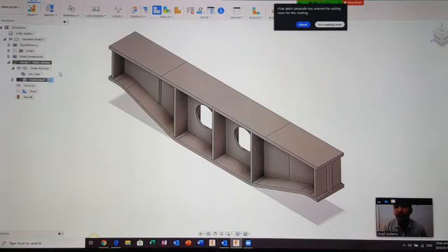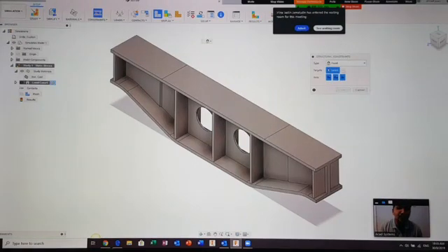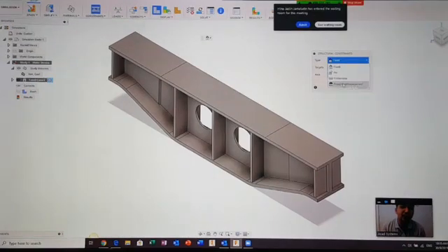Alright. So inside the cast iron material, it's already included with the properties needed inside the simulation environment. Okay, next, after putting the material, I will make the constraint. Constraint is where you want your part to stop, or maybe you want to fix the location of your part. Alright, so using constraint, it has several functions here. The type here, you can choose between fixed, pin, frictionless, or prescribed displacement. Let's say I'm using fixed.